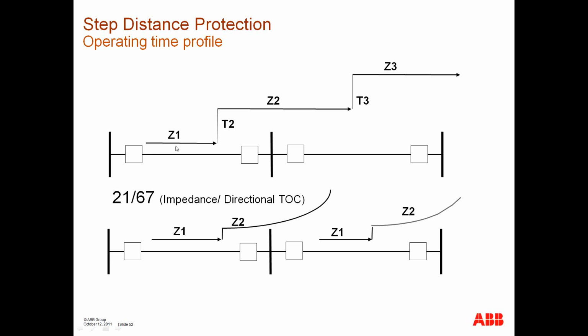Here's an operating profile using the conventional step distance, Zone 1, then a time delay, Zone 2, a time delay in Zone 3.